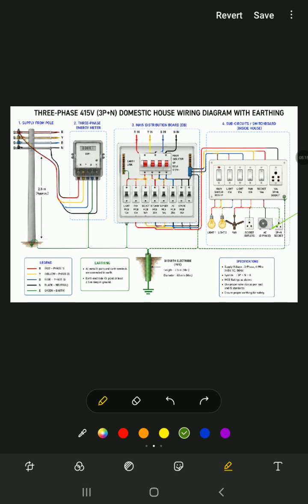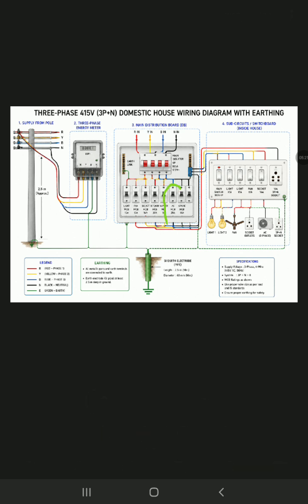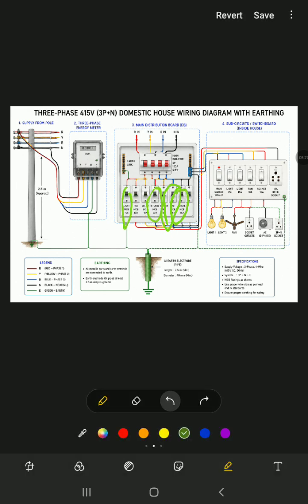In those cases we use different MCBs. Here we find that a 20 amps MCB is for AC, for others it is 16 amps, here 20, again 10, 10. So based on the division of load we calculate the MCBs. This way the switchboard is arranged.